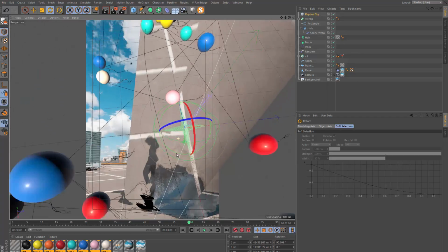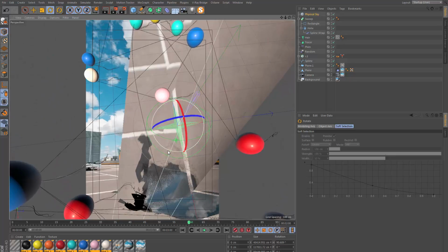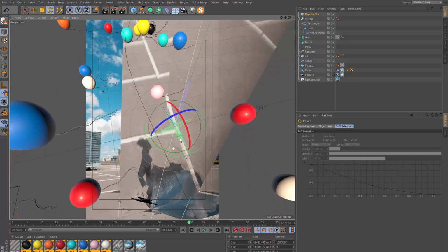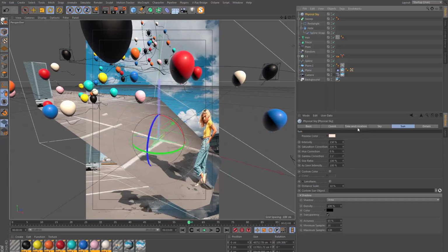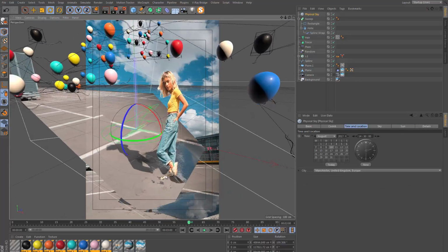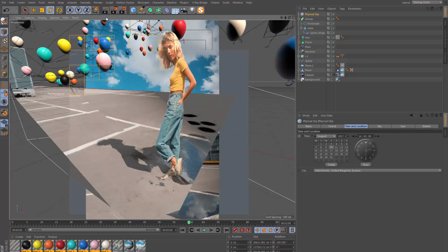And I can try to match it up to the shadow that this is casting here, so I can continue rotating this even more. And it seems about here would be correct. And we have the right angle in the sky because of the time and location settings here. So to test this, I can do a quick render and see how those shadows are going to appear.